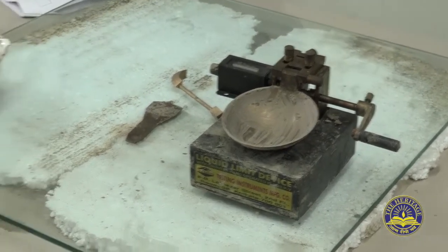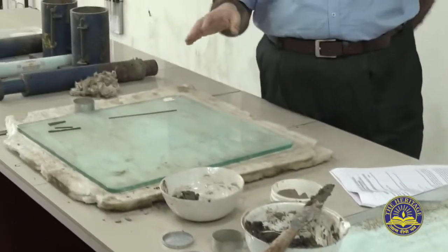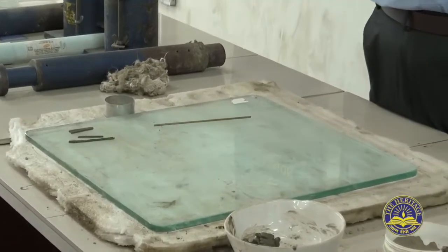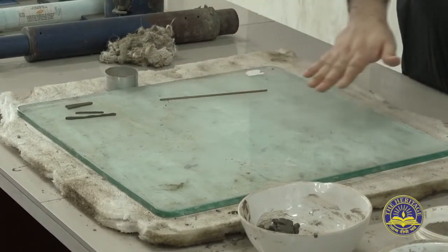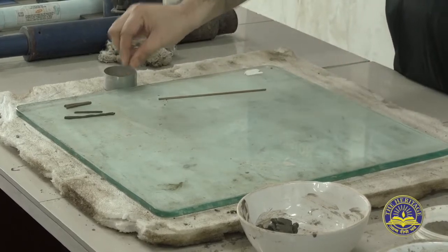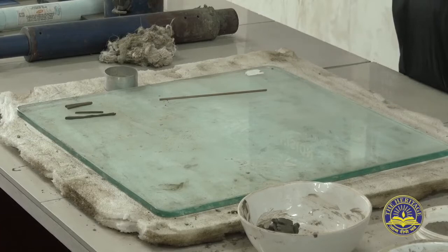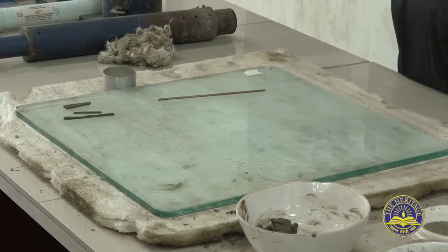Now next one is the plastic limit test. What is plastic limit? You take some amount of soil, 425 micron passing, mix with water and roll on this hard surface, and when the thickness of this thread is 3 mm, you see whether cracks are appearing or not. If cracks are appearing, then take the moisture content corresponding to that amount of soil sample, and you take the average of these three, that will be your plastic limit. So for liquid limit also, you do at least 4 to 5 samples. For plastic limit, you do at least 3 samples.